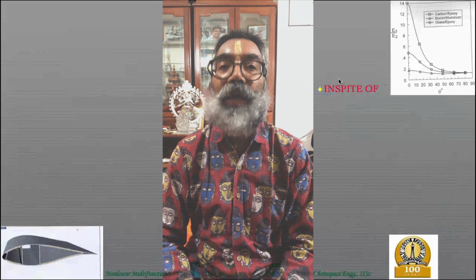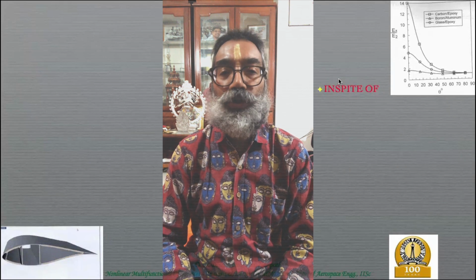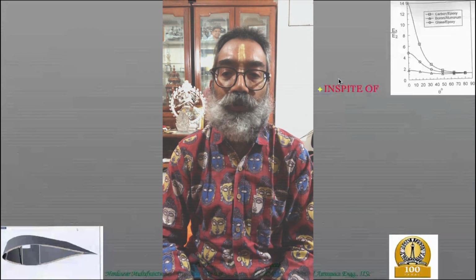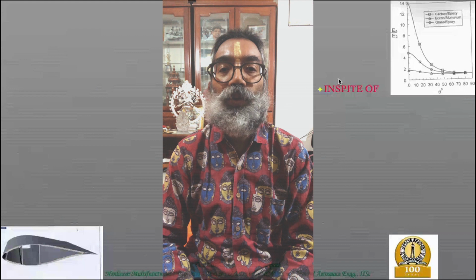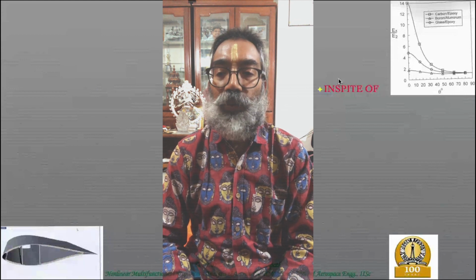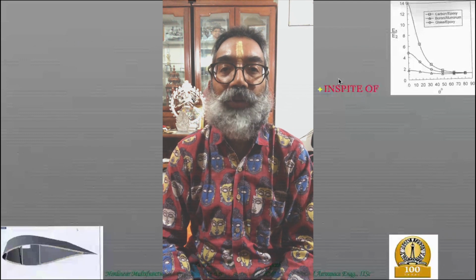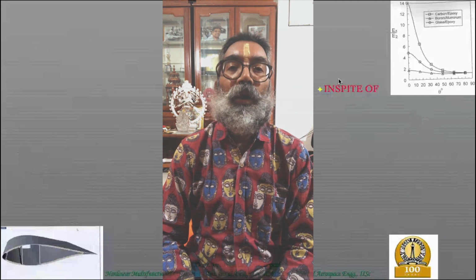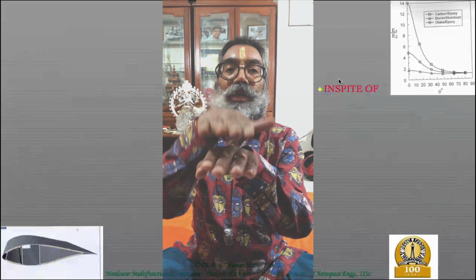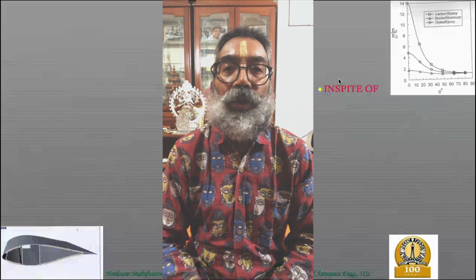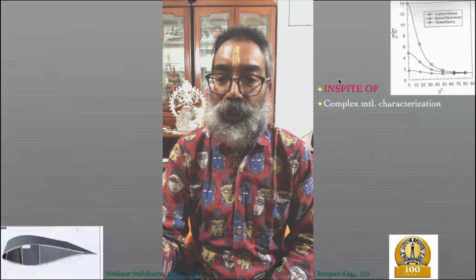But there can be off design loads, and most structures are not just having one particular load. They could have other types of loads as well, which means that you will have to design for certain strength and stiffness in the other directions as well, which is why we typically go for a laminate construction instead of just having a single lamina, or stacking all laminas in the same direction. We tend to have them in different directions so that you take care of certain off design directions as well. So that's what we look at first.